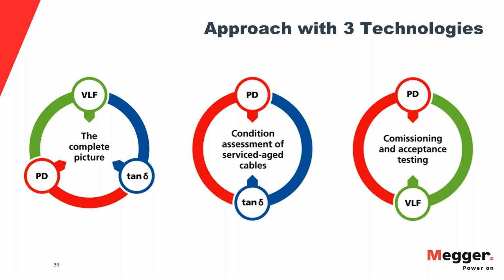This should be avoided, but it's possible to get there. While in IEC, no, it's U0, and the tan delta is what you do: 0.5, 1, 1.5, and 2 times U0, and the withstand is 3 times. So much easier. But yes, it should always be to U0, which is the rated phase to ground voltage.